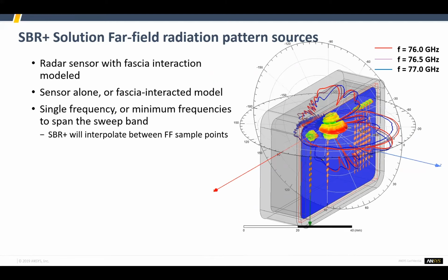So what we're looking at here, that little radar array, those two linear transmitter arrays plus that receiver array off to the right, we are modeling that and the enclosure that it is in directly in HFSS, the finite element solver, right? Once that is done, the solution to this model will then become a source for the scenario model that is implemented in the SBR.